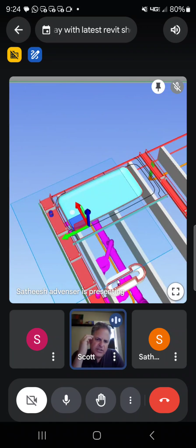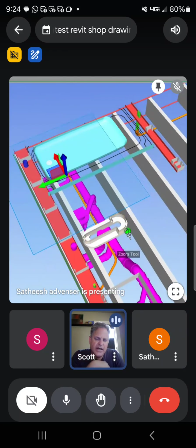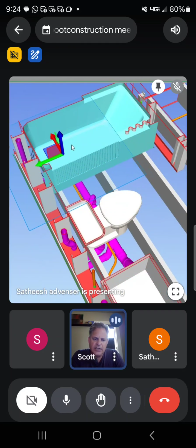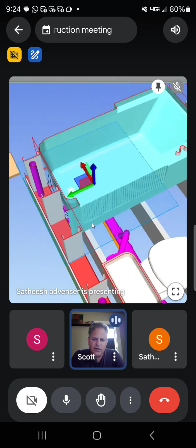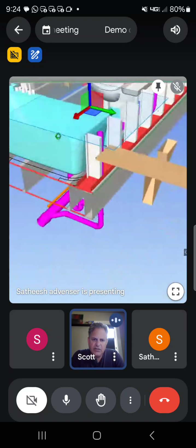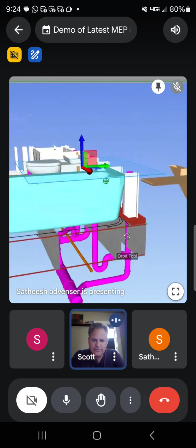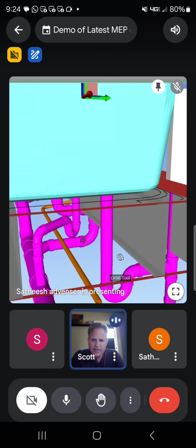And in reality too, the tub is going to have an overflow. These are things that we'll have to work out as you go. The tub will have an overflow, and normally that plumbing piece gets slid all the way back close to the tub.